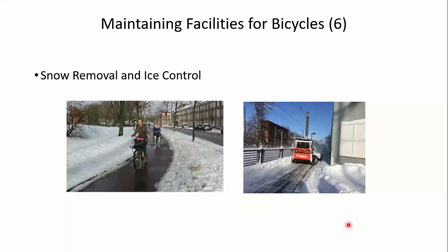But as Nicholas suggests, people ask, well, why do we have to upgrade the curb ramps if there's a big maple tree heaving up the sidewalk mid-block? People can't get from one intersection to the other. But if I have to do that too, as part of my resurfacing project, when will it end? I might have to rebuild every sidewalk in town. And so I follow that logic. But basically, Kinney versus Jerusalem and DOJ and FHWA say that when you do a resurfacing project or an alteration, you need to upgrade the curb ramps at the corners to bring them into compliance.